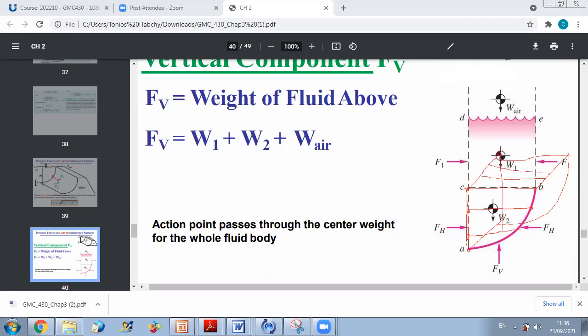Okay, so now I will draw for you the projected surface. The projected surface has a height of CA and has a depth D equal to the depth of my surface. So if you have a depth of your surface D, when you project on the vertical plane, you will end up with a rectangular area. And we demonstrated together that the horizontal component of the force exerted by the curved surface on water is equal to the horizontal force acting on the projected area.